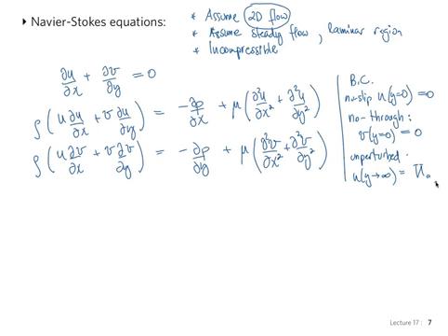So even though we have the full set of equations and boundary conditions, and assume 2D flow, steady, incompressible, even under these circumstances, already for this flow, there's no solution. We can't just write it out like that. We have to still make a few more approximations so that we can get a solution.